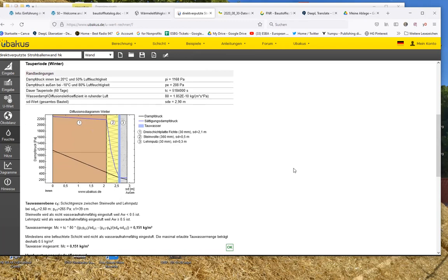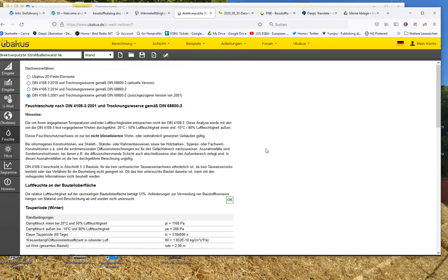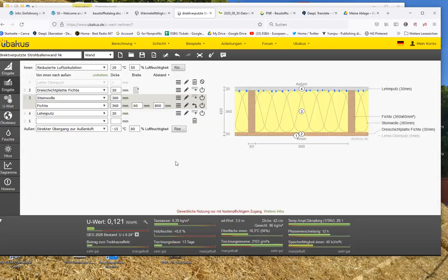In whatever example, you have a castle with really solid rocks, super thick. The sun is coming in summer and they're heating up for weeks, and the phase shift would be some weeks until they cool down in winter or in autumn. Yes, you can try it out. There's an example wall just made of stone or concrete or whatever. I mean, the phase shift will be less, but the storage capacity will be higher, much higher. Okay.